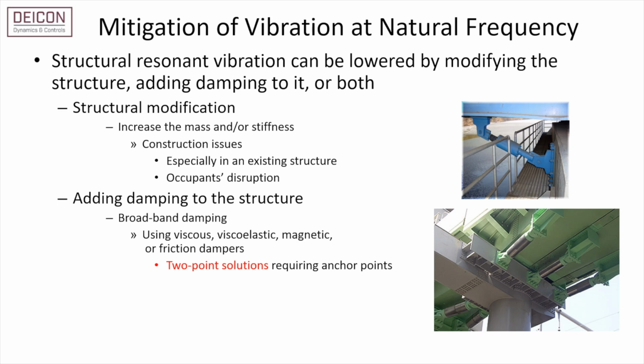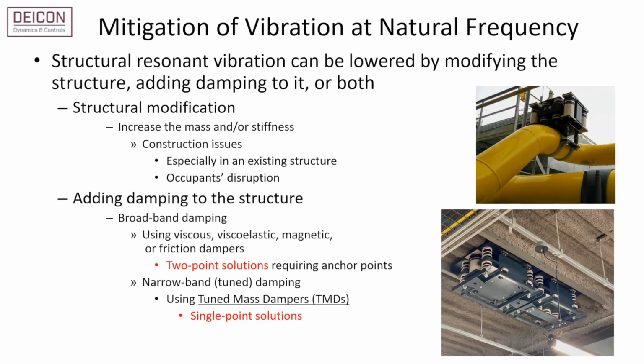In certain applications, like when dealing with vibrating pipes at elevated levels or bouncy floor systems, there might not be a support structure for dampers to attach to. In such cases, tuned mass dampers serve as an alternative. These single-point damping solutions don't require anchoring points. They are tuned devices targeting a single mode of vibration and effectively adding damping to it.